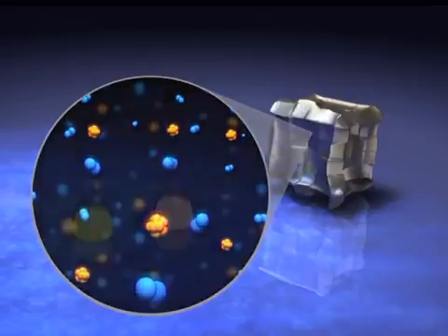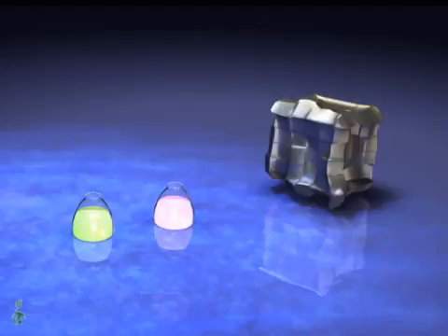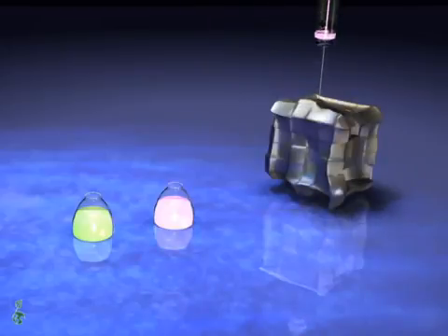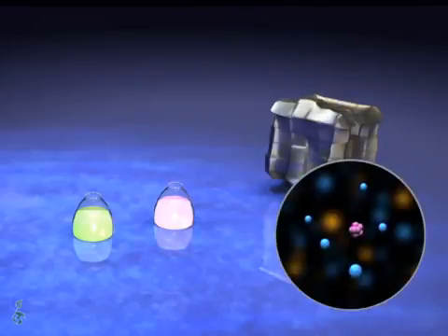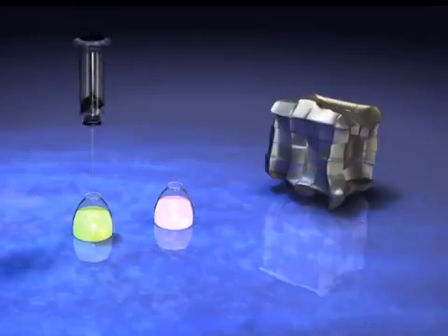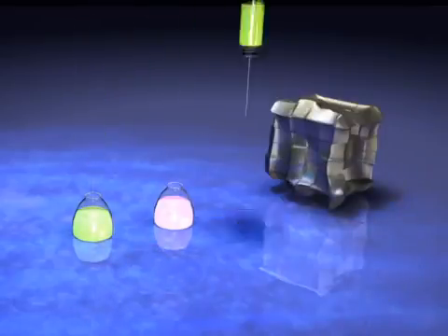provide an electric current. Impurity atoms are incorporated into the material to increase conductivity. This procedure is called doping. Doping is, for example, possible with pentavalent elements such as phosphorus, but it can also be realized when trivalent elements such as boron are used.